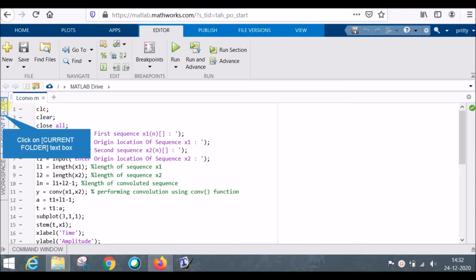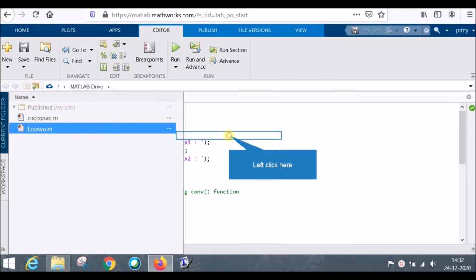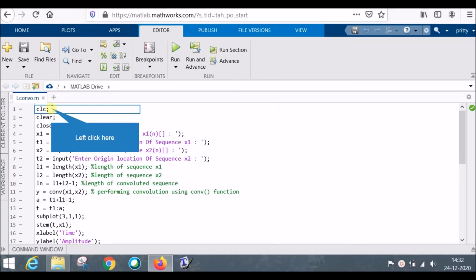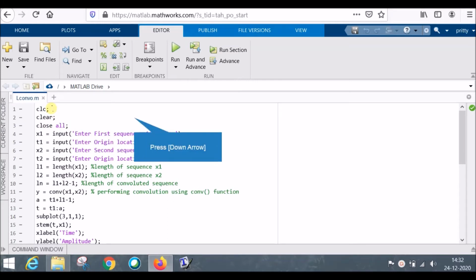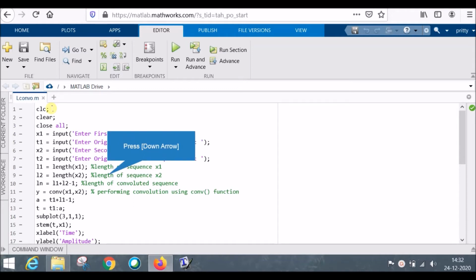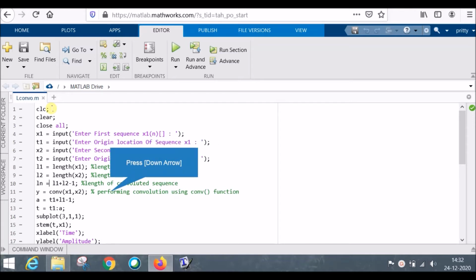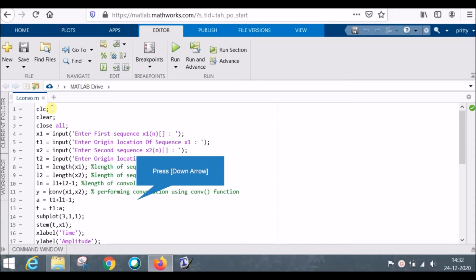First of all, we are going to do linear convolution. What's the difference between linear and circular convolution? Theoretically, you will say it's a difficult task. But in simple terms, linear convolution is simply the tabular method, and circular convolution is about taking two sequences in a circle, rotating one clockwise, then multiplying, checking, and later adding.